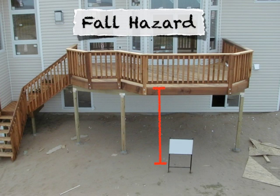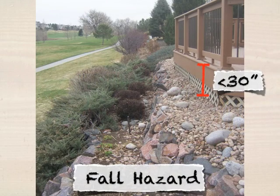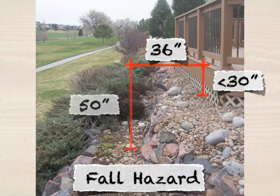Previously, deck height for determining if guards were required was measured from the edge of the deck, and that worked fine for decks like these. But situations like this, that were obviously a fall hazard, could be built with no guards. With the horizontal 36-inch measurement, the place where height is measured from now better represents the actual hazard.